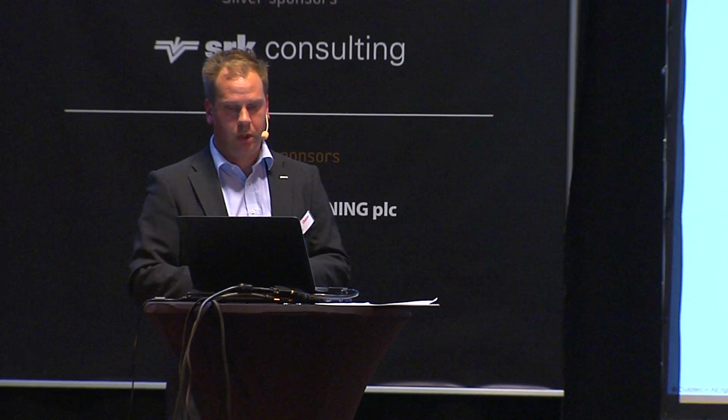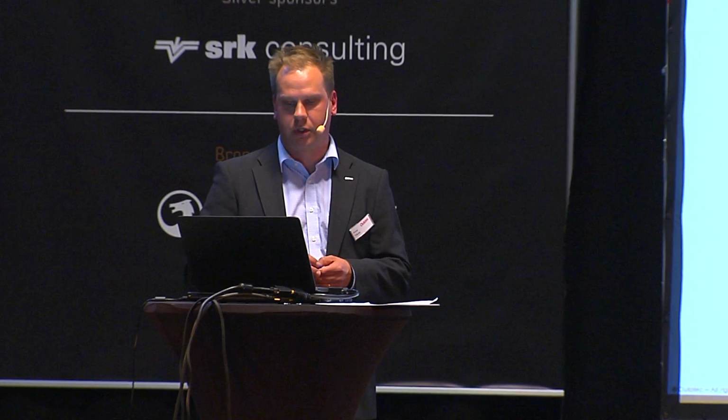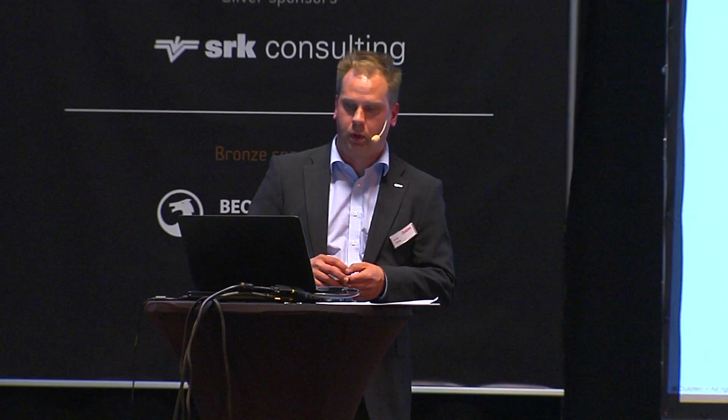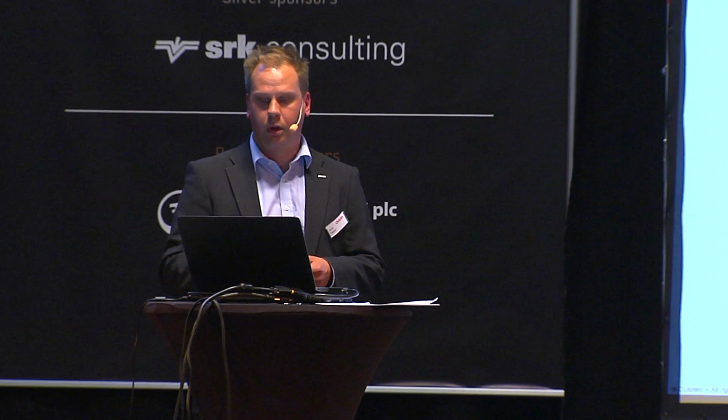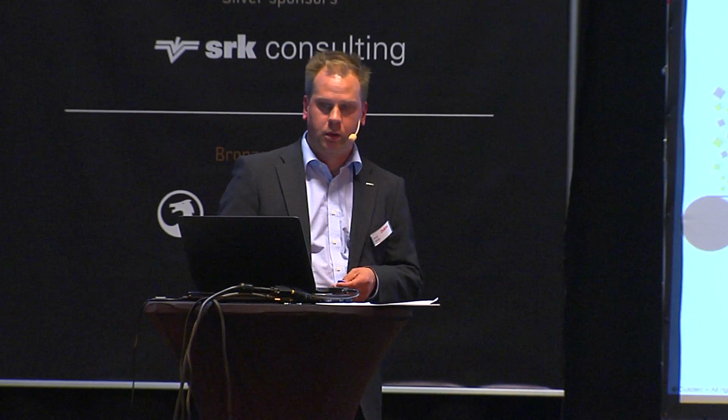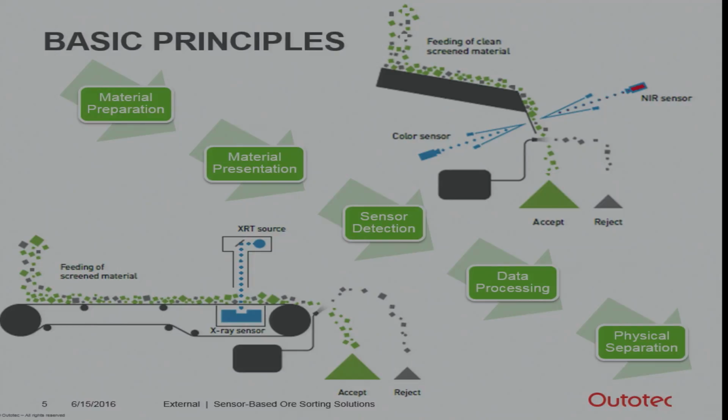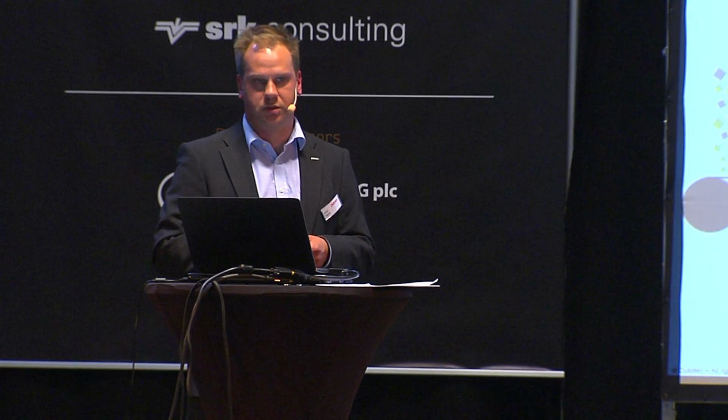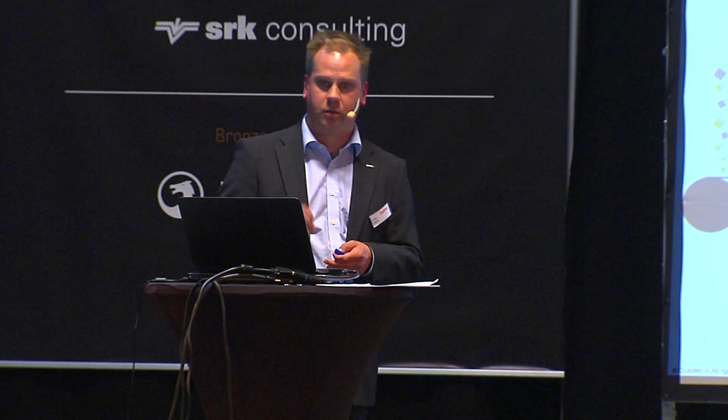There are other benefits as well, like no chemicals are needed in this process, and there must always be a screening to get the right sizing for the desired application. And on the ore types where the separation with the sorter is based on surface quality, it always requires washing. So the basic principle of ore sorting is that material is prepared by screening and possibly washing. Then it's presented to the sensors. Sensors do the detection. The data gets processed in a matter of milliseconds, and then there's a physical separation event. In these sorters, it's most typically a pressurized air nozzle that will shoot the rock away.